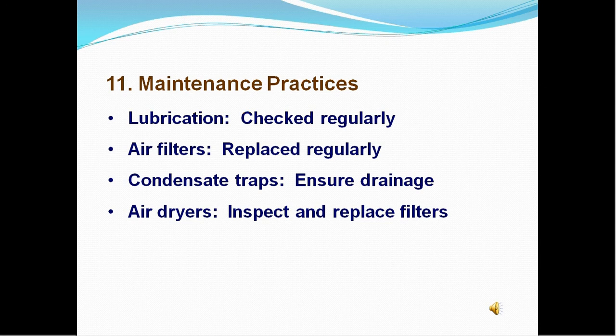Condensate traps. Many systems have condensate traps to flush condensate from the system. Manual traps should be periodically opened and reclosed to drain any accumulated fluid, and automatic traps should be checked to verify they are not leaking compressed air. Air dryers. Drying air is energy intensive. For refrigerated dryers, inspect and replace pre-filters regularly, as these dryers often have small internal passages that can become plugged with